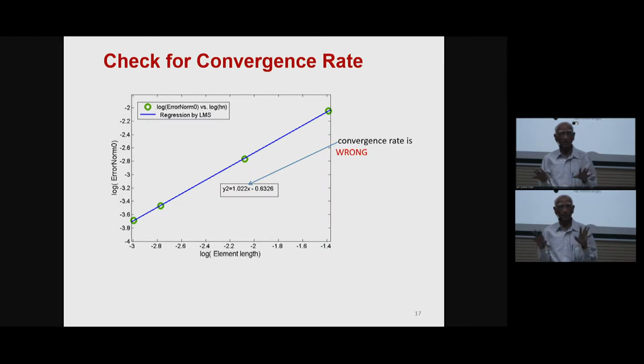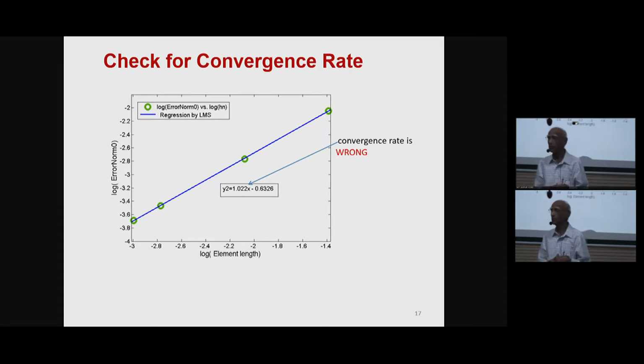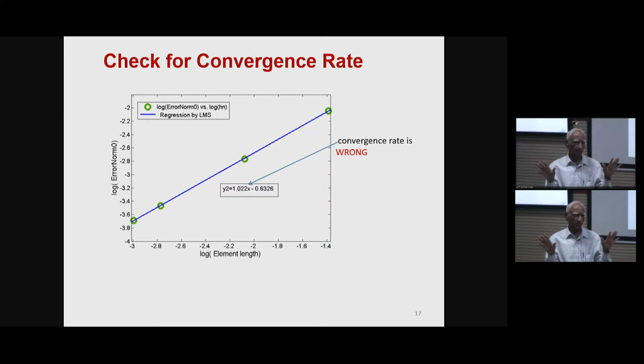They are most accurate at Barlow points, B-A-R-L-O-W. His question was where they are most accurate, not where you should find them. So if you want to say where they are most accurate, again we are talking about linear elastic problems, they are most accurate at Barlow points. And where are Barlow points? That depends upon which element you are talking about, whether it's an 8-noded element or a 4-noded element. Again, these are two-dimensional problems.